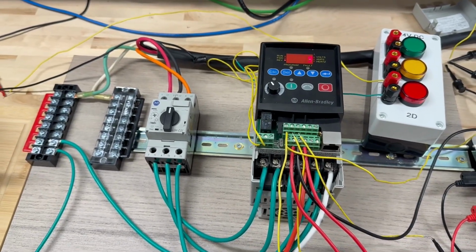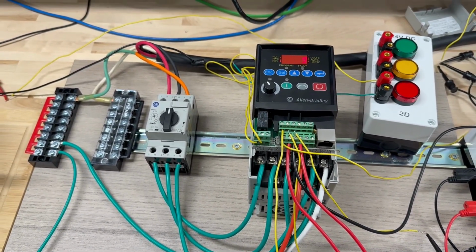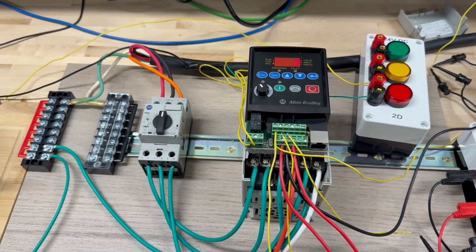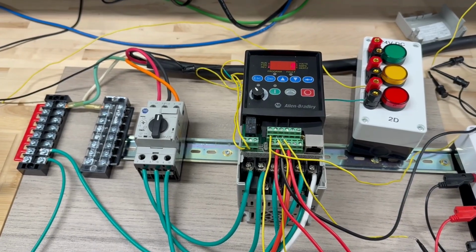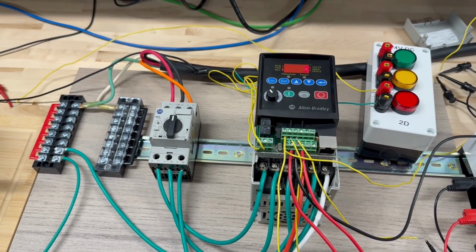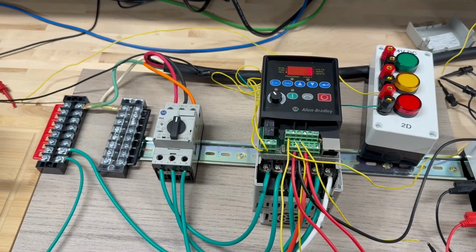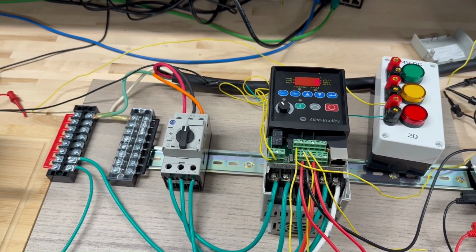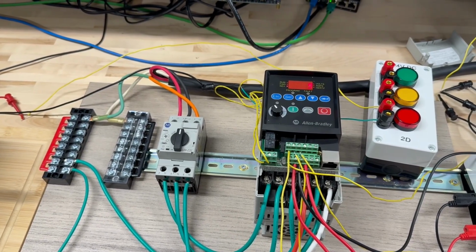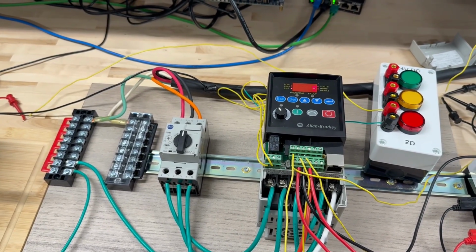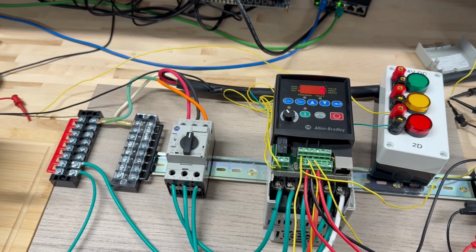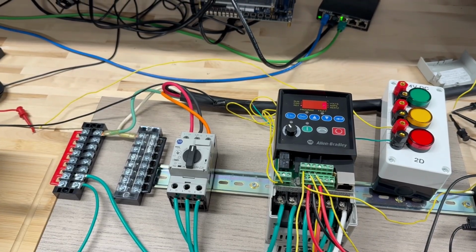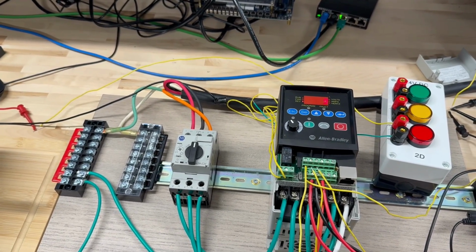if you put 9, you can say to the relay, if you get the error, first you can tell how many times it should retry, meaning reset the error. For example, let's give 2 times. If I get the error, it resets 2 times. Also you can give a time delay, how much time after the error before it resets again. Let's say I give retry 2 times and time delay 5 seconds.